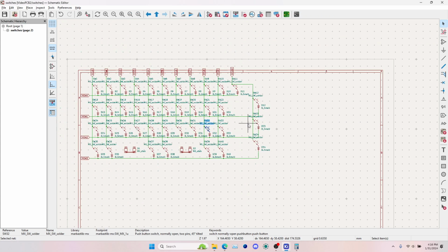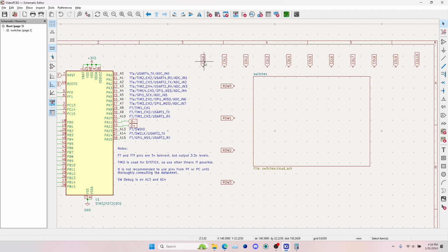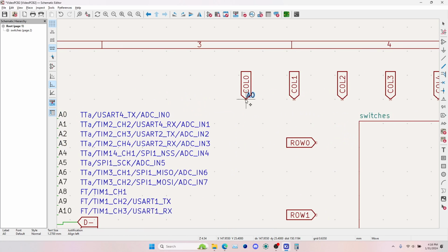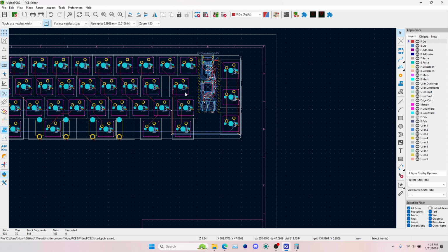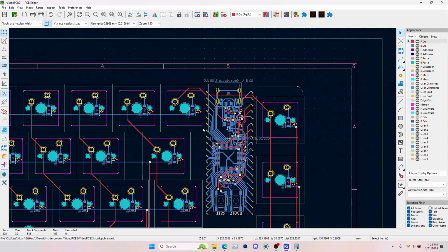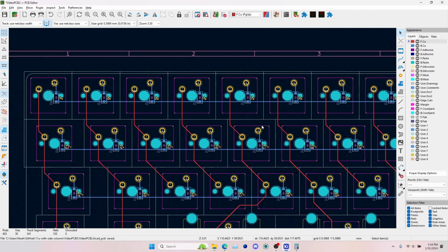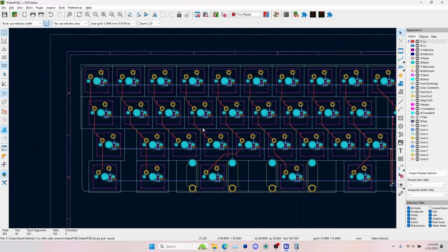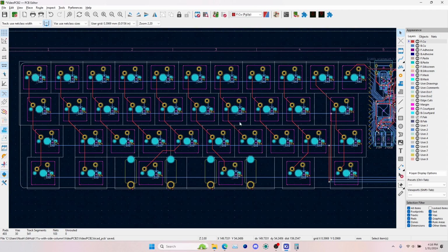And we're going to do that by connecting our rows and columns to these labels here. These can come off with Control-C, Control-V, and I can connect A0 to column 1 or column, whatever it is. So let's go to our PCB and just find the pins we want to use kind of in line with the columns that are existing. So do we have, what was it, 12 columns? No, 11 columns and 4 rows, so 15 pins.